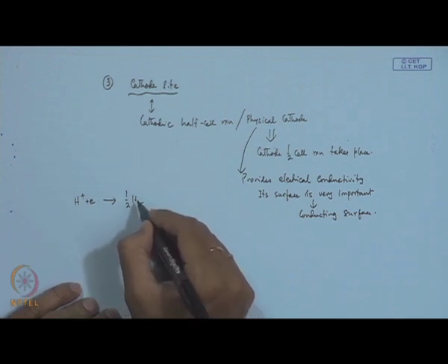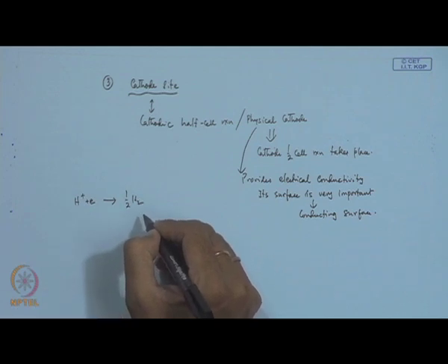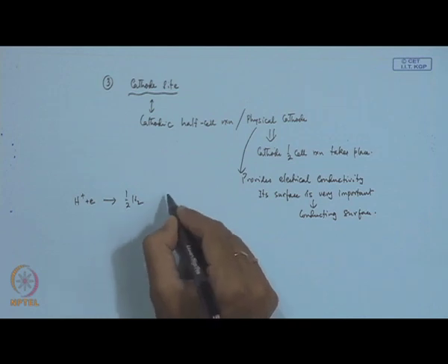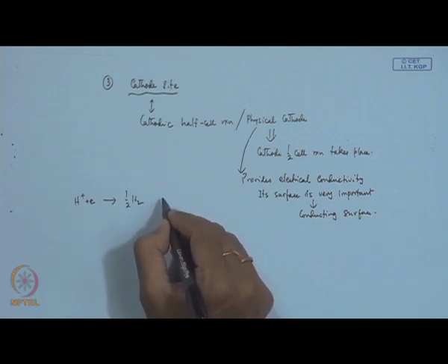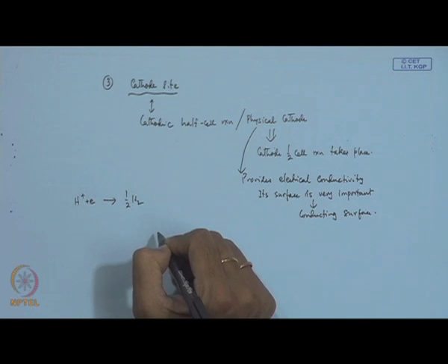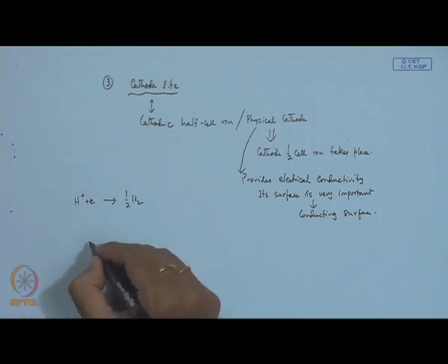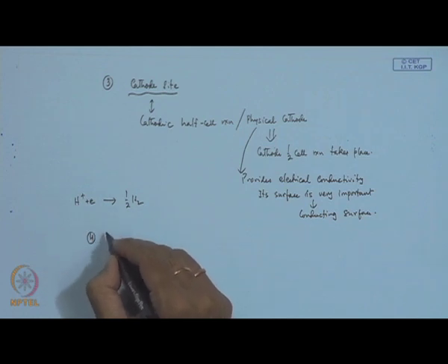And this distinction between cathode reaction and cathode material is important when we look into localized corrosion. Okay. Localized corrosion means the corrosion is very much localized in nature. Basically it may be thought that the regions which are not corroded may be cathodically protected. Next, the fourth one, is ion transport.